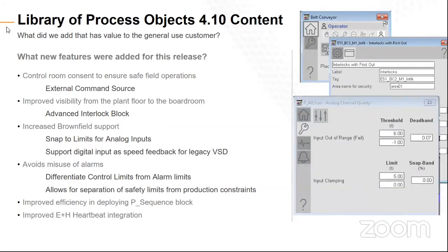And it's one of those things that if you've seen it in Studio 5000 and inside of the process library objects, you're not necessarily required to use the latest and greatest, but if there's something that you can add there, you can import and export different versions of it. So if you're starting from scratch, obviously you download the latest library, put that all into your system. But if there's a feature set in the new library set and you're commissioning or you're supporting something that's older, there's a potential that you can just add that one object that you're missing.